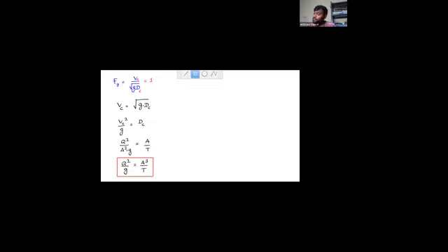If you want to make sure the flow is a critical flow, the must-and-should condition required for critical flow is Q squared by g equals A cubed by T. Keep that in your mind. It is not going to stop here. It is going to stay with you throughout the chapters, and this is very, very important. So this is known as the critical flow condition.